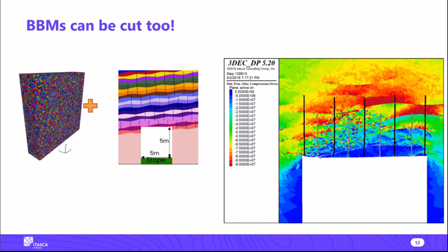In this particular case, these were wavy, I think they were probably veins, and we were able to cut these wavy shapes into this tetrahedral model, and you end up with a result like you can see on the right-hand side here, where you have all these little tetrahedra that are potentially cracking and falling apart, but then you also have movement on these larger scale joints. As you can see, the stress discontinuity there across some of these wavy joints. So you have two layers of discontinuities going on in these models.